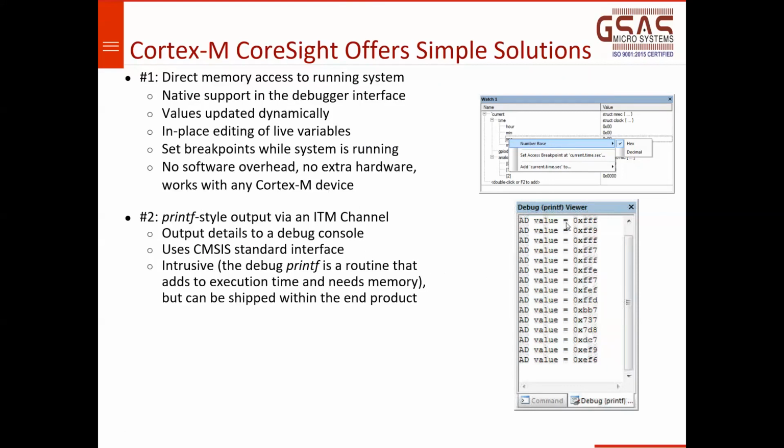When you use these printf statements, the output is not routed through UART, but it is routed through the debug log.